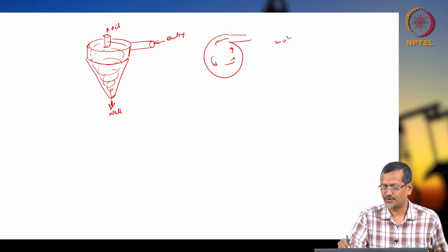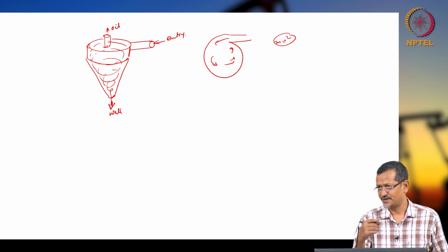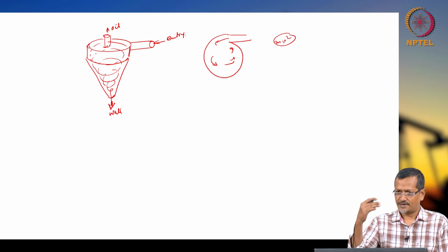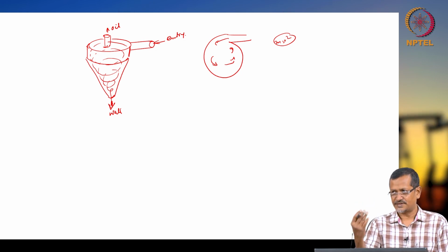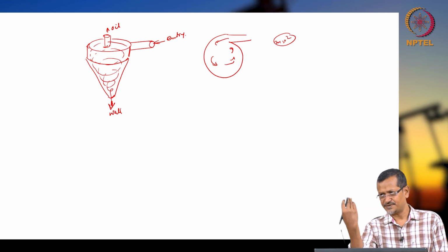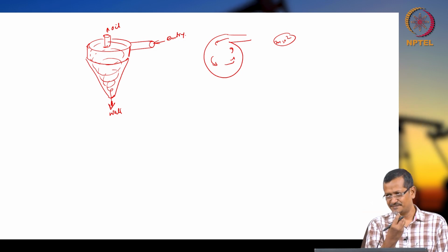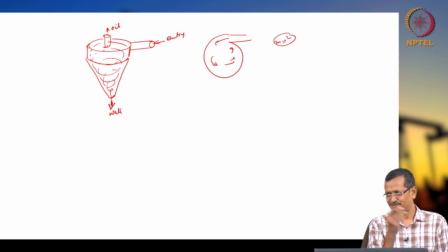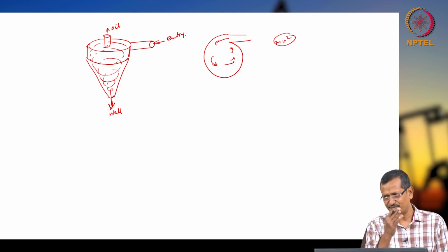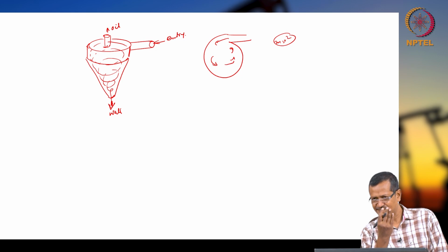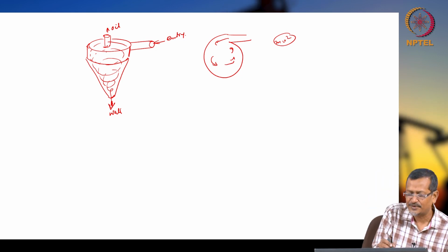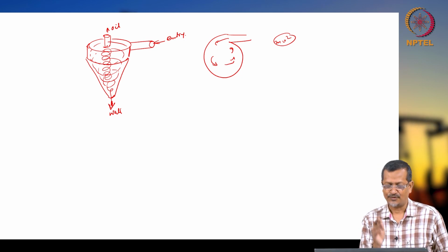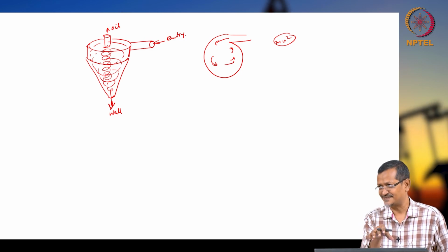The mv square formula, you can see the centripetal force, right? You can remember it from school books. Because of that centrifugal force, water will be touching the outer surface and oil will try to touch it, but it will not get space because water will take the space, because oil has lighter density. So, oil will try, but it will not go. Oil will be rotating at the center actually. Now, you have got oil and water separated inside the system.